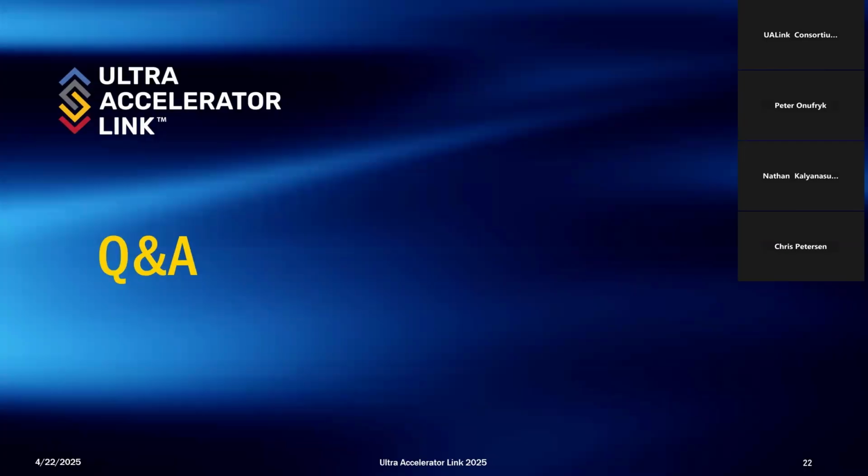Excellent. Thank you, Nathan. Our next question is, is UALink cache coherent? I can take this one. No. So UALink is I/O coherent. It is not cache coherent. It is software coherent, and it has only simple load stores and atomics. There are no snoops which go across the UALink.